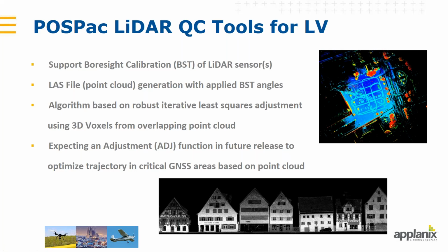You can apply the boresight angles or not, depending on what you want to do. The algorithm used here is based on a robust iterative least-squares adjustment using 3D voxels from overlapping point clouds. For those of you who are familiar with photogrammetry, it's quite a similar process.